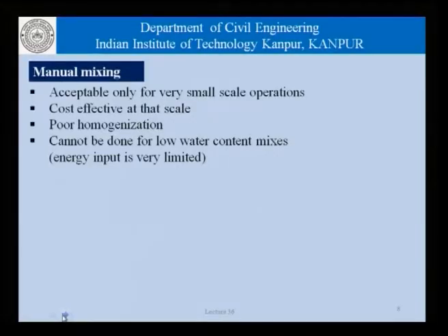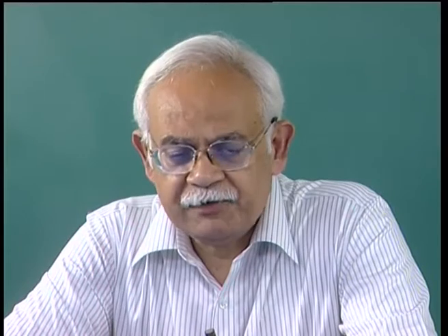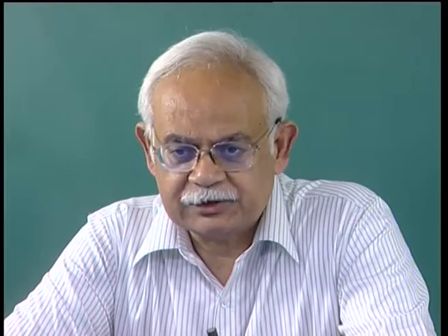Of course, the way hand mixing or manual mixing operates, we can only expect poor homogenization. We cannot expect a very homogeneous mix at the end of a hand mix process. The whole process, as far as hand mixing is concerned, as a matter of fact, cannot be done for low water content mixes. The concretes in that case are so stiff that it is simply beyond the power of an individual to be able to mix the concrete. And by that token, when we are doing the manual mixing in concrete, we invariably land up using a large amount of water.